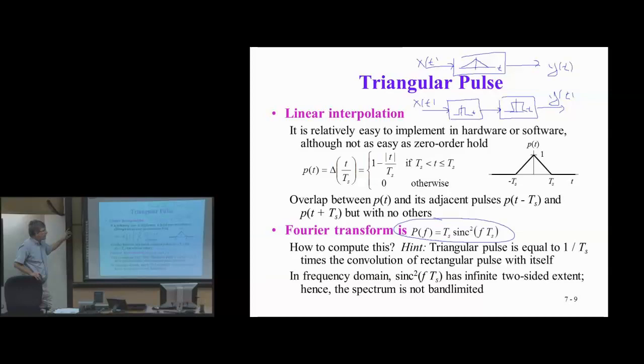All right, so what's the stop band attenuation for this filter? 27 dB would be correct. How do we get that? In the Fourier domain, I have two LTI systems in cascade, which means their frequency responses multiply: Y of f is H1 of f times H2 of f times X of f.